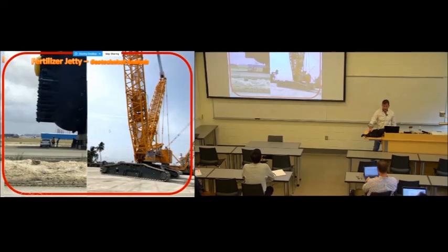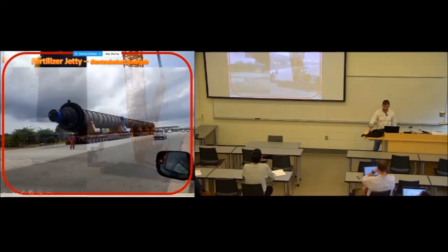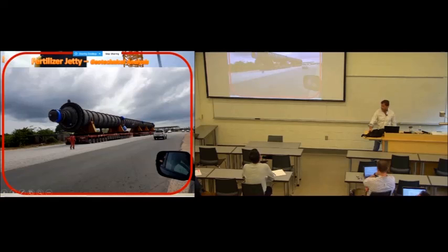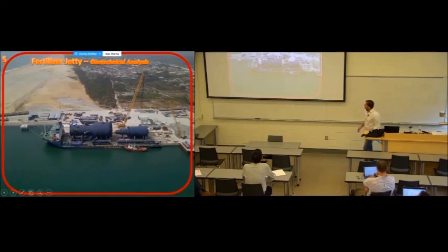Other high loads are the cranes. This is one of the risers that were offloaded onto the jetty. And that's another aerial picture of the ships that are expected. And the 100 ton per bollard, you can see from the ropes here. These will pull in case they hit the fenders or there's wave action. The expected maximum lateral push or pull is 100 ton per bollard.